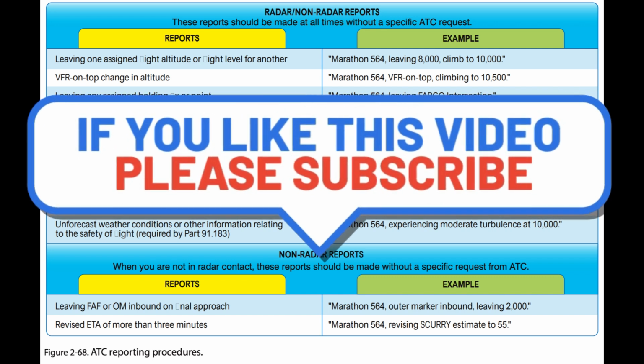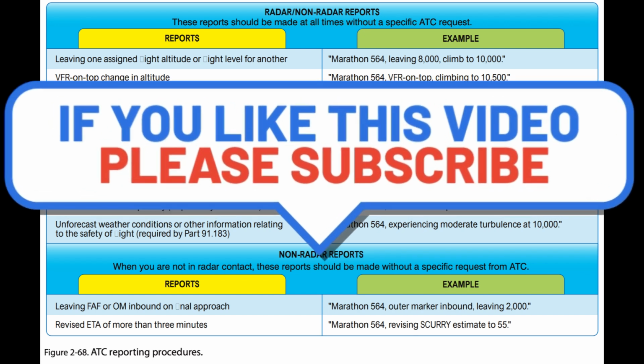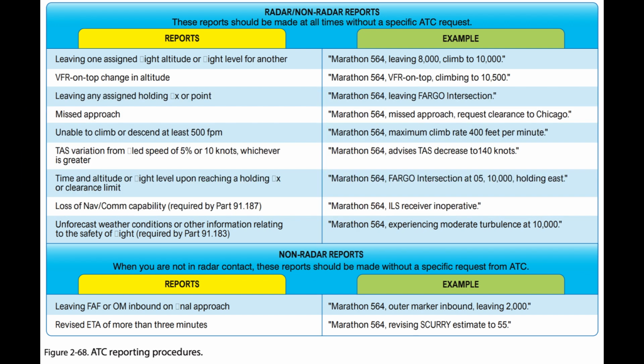When an oral or a light panel indication is used to determine the time passing a reporting point, such as a fan marker, Z marker, cone of silence, or intersection of range courses, the time should be noted when the signal is first received and again when it ceases. The mean of these two times should then be taken as the actual time over the fix. If a position is given with respect to distance and direction from a reporting point, the distance and direction should be computed as accurately as possible. Except for terminal area transition purposes, position reports or navigation with reference to aids not established for use in the structure in which flight is being conducted are not normally required by ATC.